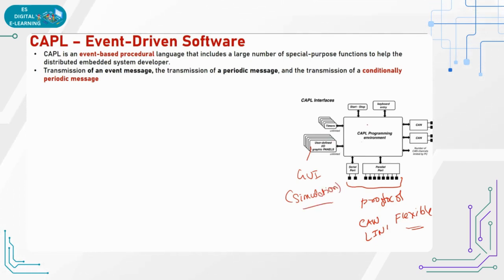The backend is the CAPL program, and the timers, specifically on start or periodic timing, come under timers and start and stop. In CANoe we have start and stop; whenever you press start and stop, the tool's backend has CAPL functions. These CAPL functions make the complete panel work.